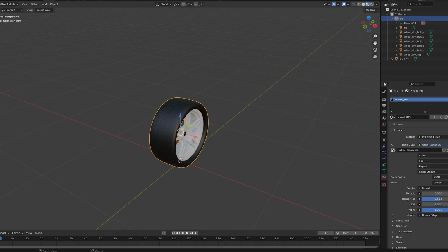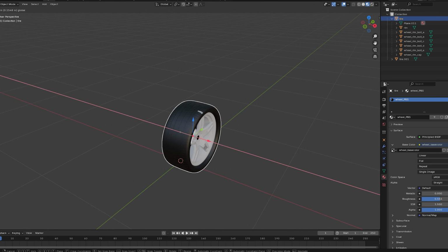Now that we have the polygon count addressed, let's continue with other ways to ensure you have a clean 3D file, starting with merging your vertices. It is recommended to merge your vertices so that there are no polygons that aren't attached to your model. You can check to see if your vertices are merged by selecting your model and moving it around the world space to see if any polygons stay behind, like we have in this example here.